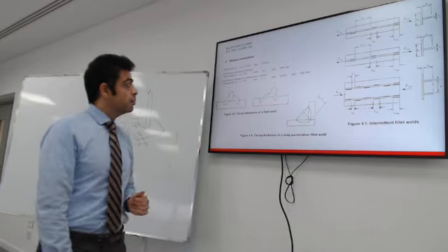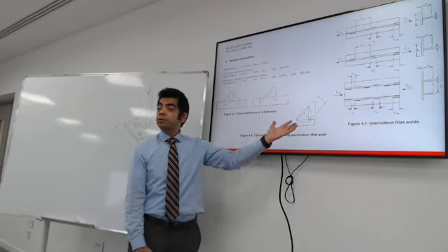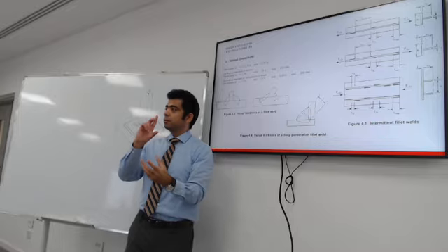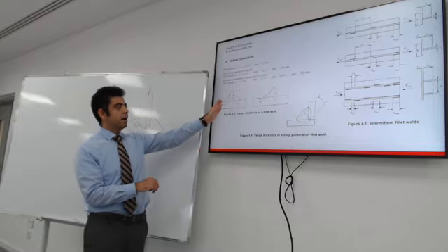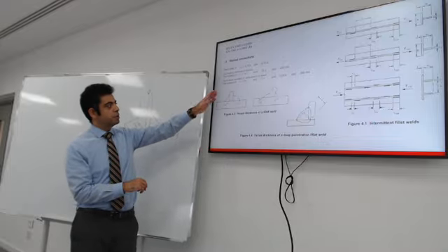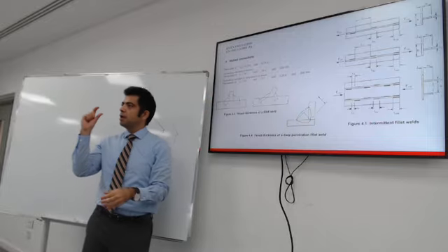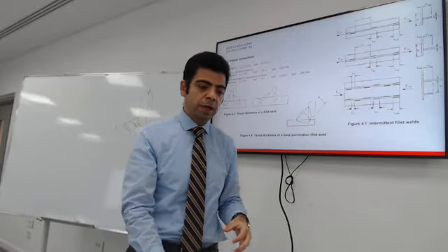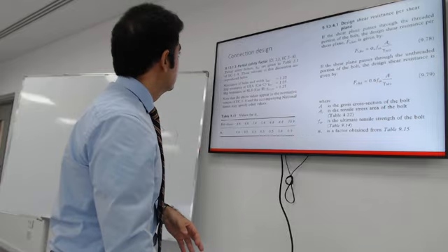This is the welding part. The code tells us where the effective throat is. It's the diagonal, as we talked about. And what if the surface has different shapes? It's concave or convex. Where would the effective throat be? It's very important to keep these in mind. All right.